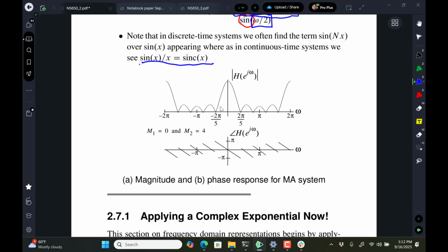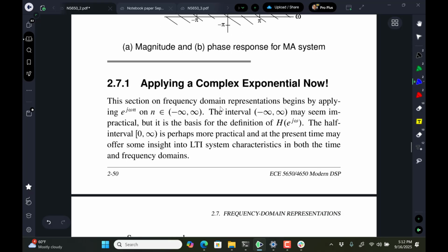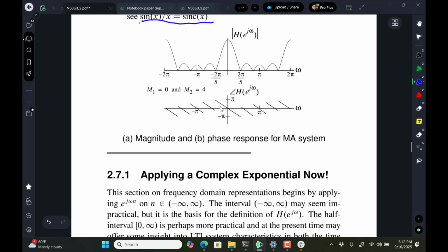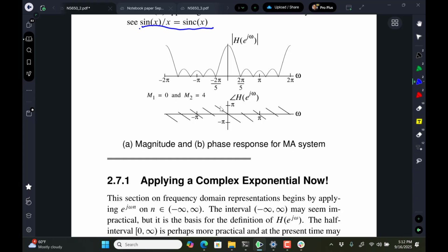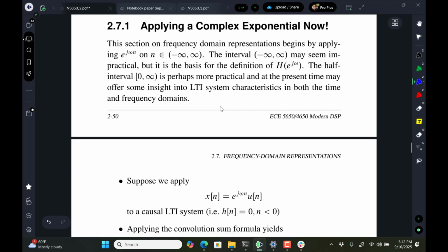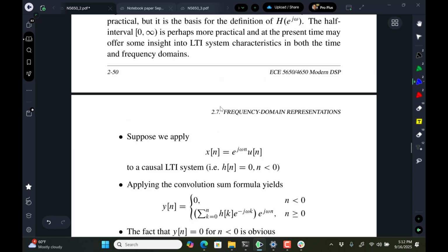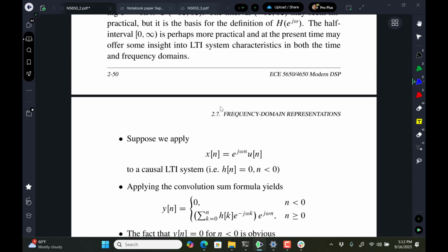Is that believable? So that's why I will call it then this aliased sinc function becomes the sine nx over sine x. Right now, is that satisfying? It is like a low-pass filter. It's an averaging effect, and it's just the discrete time version of what we'd have for a moving average filter if you created it in analog electronics.